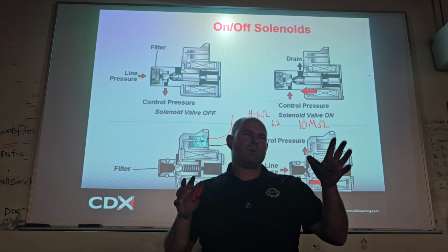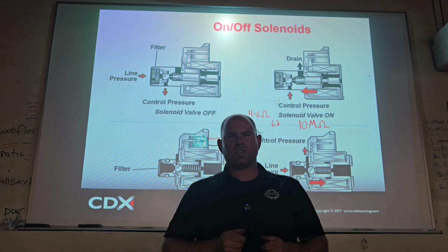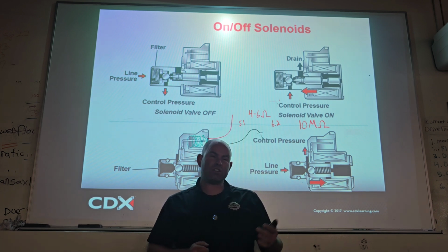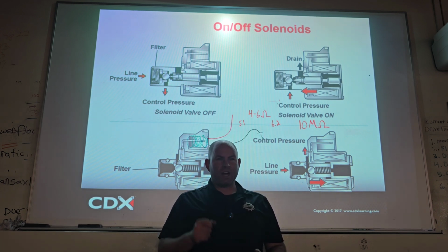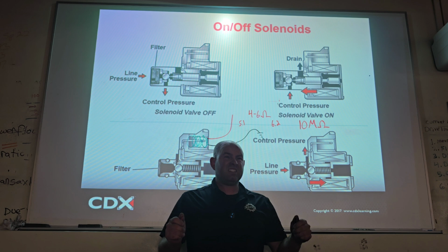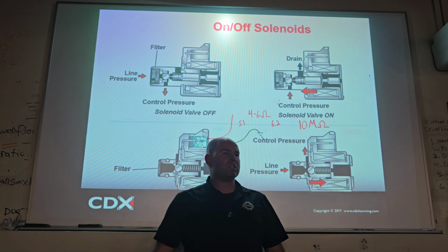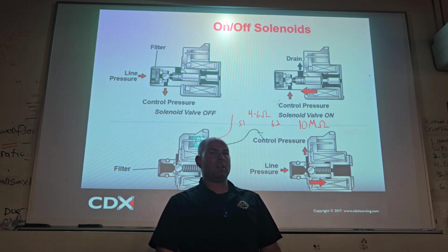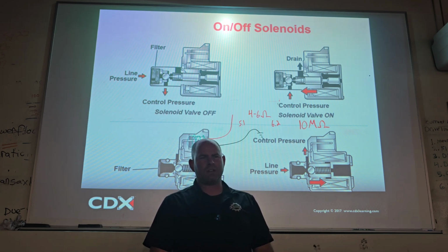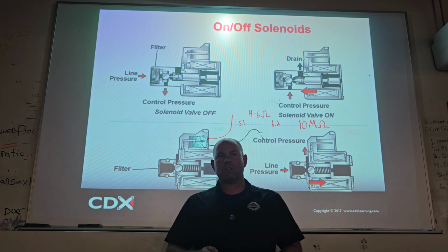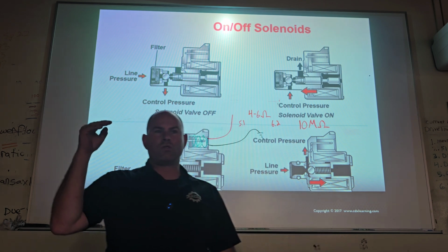Now, does anybody remember what the defect or what the customer concern was back when I told you that story? Remember or no? Another Jeep, different 96. Put it in drive. First. There was no second. Second never showed up. Except once in a while, it'd be like, bam, second. But then the next time it'd be stuck in first again. Do you see why a shift solenoid would cause that now that we've discussed a little bit about what shift solenoids do? That shift solenoid needs to control the application.